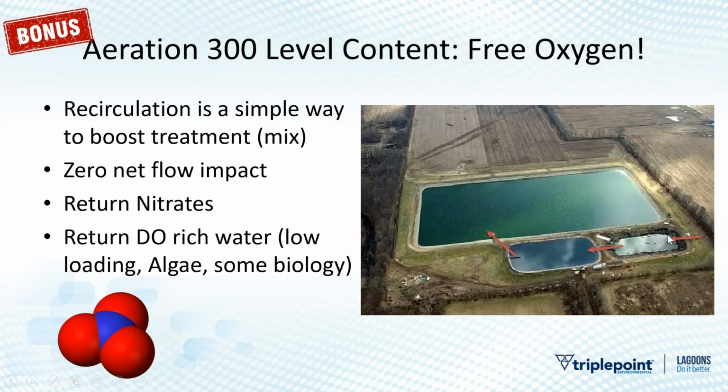So you have a lagoon system here. They've drained it to desludge, but we'll say they install some aeration right here. The water comes in. We have BOD treatment, goes to cell 2. We've got BOD treatment there, and moves to cell 3 for nitrification. Usually nitrification happens at a later stage when the BOD is low. So you'll see nitrification happen out here.